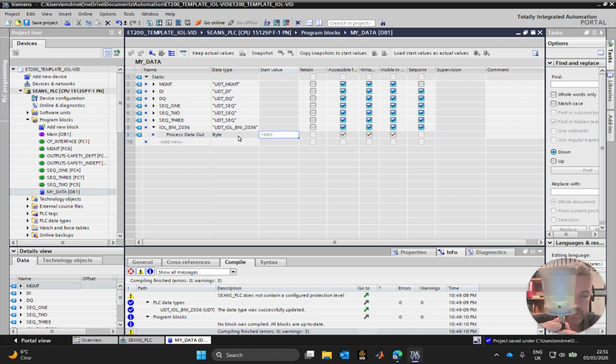So it has to be communicating for that. Where it was solid green, just indicating that it was powered and not communicating, it is now intermittent. It's a flashing green, showing that it's not only powered, but it's also communicating with the PLC, exchanging data.